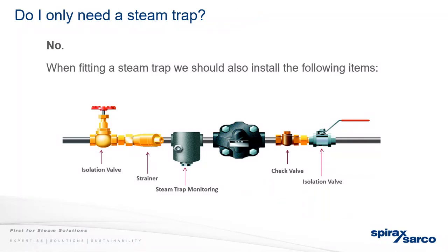Just one of the questions again: what is the best type to use on a condensate recovery line, especially when the recovery line has no pumps? Well, in a case like this, what you're seeing in front of you is probably from a process side, from a steam main line. You could probably use something like a thermodynamic trap, because you need quite a lot of them in a larger installation, let's say more than 100 meters.